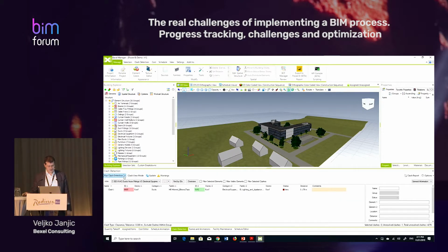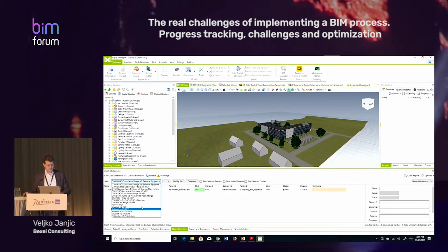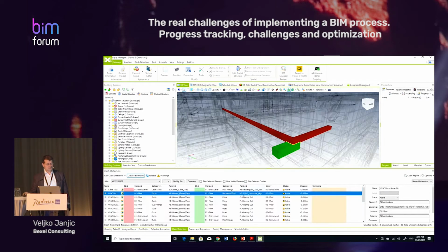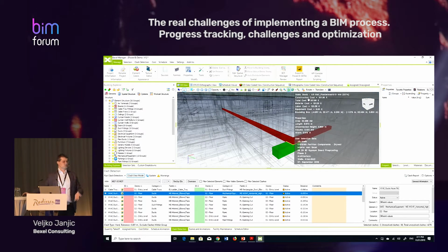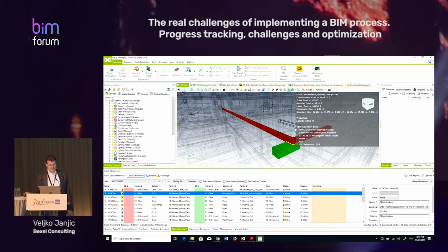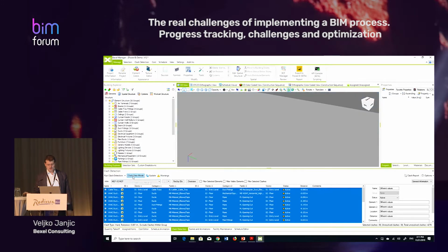Okay, I'd like to see the clashes. Standard, like in Navisworks or Solibri, you can define clashes. Clashes are there, okay, clash view mode. You can identify clashes, differences, clearance, tolerance, a number of things could be done. And what is again good via BCF, just send them to, let's say, the BIM authoring tool. In this case, I think Autodesk Revit was used. You can send this information to the designer, and then he can correct it. You can define the deadline, who is responsible, and so on. So these are the clashes. Not rocket science, but a good thing to have.